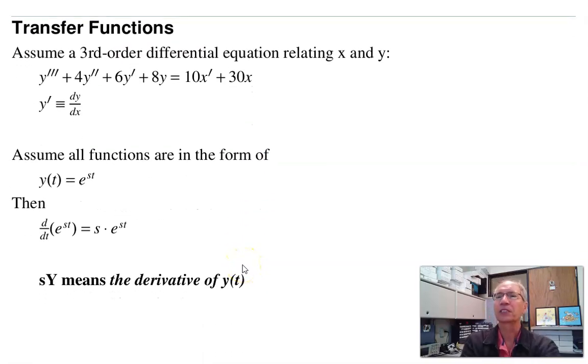Now, with filter designs, instead of dealing with differential equations, we deal with transfer functions. It makes the analysis a whole lot easier. So suppose I have the following differential equation. It's a third-order differential equation relating x and y. The basic assumption is that all functions are in the form of e to the st. What that does is when I differentiate, I get s e to the st. So sy means the derivative of y.